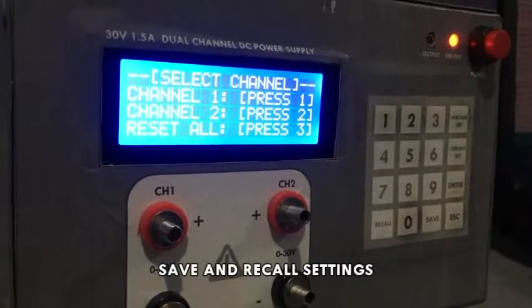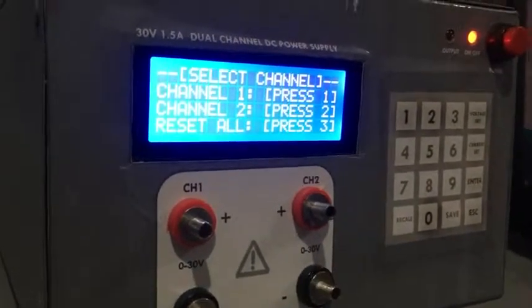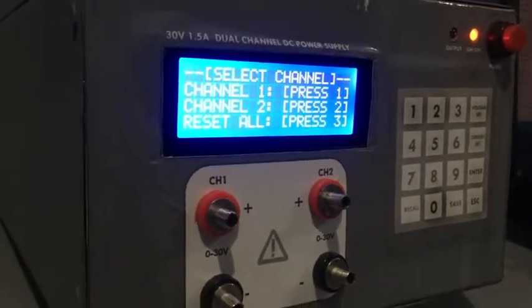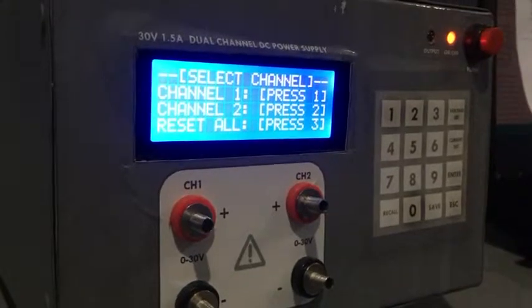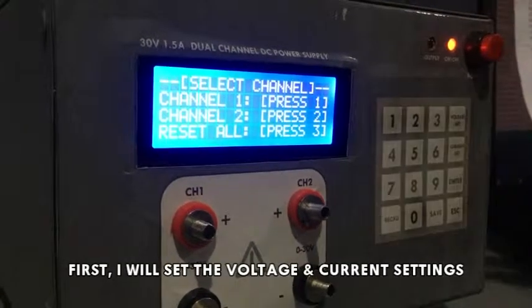In this part, I will demonstrate how to use the save and recall settings. To ease the time of setting the voltage and current with the same value or input again and again, we can use the save and recall. I will set channel 1 and set the voltage and current.